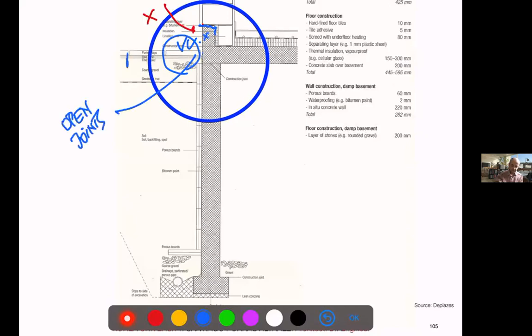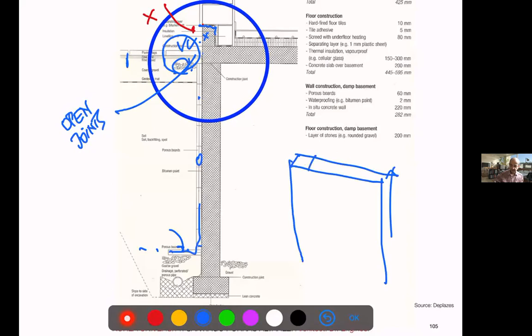So open joints everywhere, so the water will filter, and we have still the gravel, the drainage wall, and so on. Here, instead of that felt, we have drainage elements. It will act also as a filter. So very often, these are prefabricated elements with hollow spaces, and those walls are porous, so water can go through, but not the dirt. So this could have such a filter.